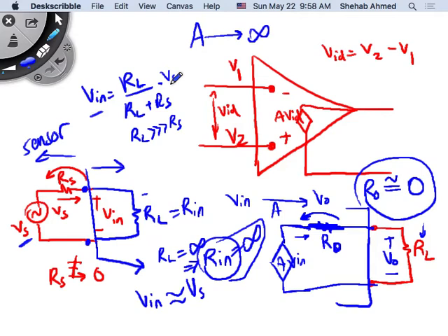So then the equivalent circuit becomes like this. We have an equivalent circuit for the input that looks like this, and an equivalent circuit for the op-amp output that looks like this. This is very similar to the voltage amplifier equivalent circuit that we introduced in chapter 1. And this is the workhorse of the op-amp's equivalent circuit. We will utilize this equivalent circuit, which is basically an input impedance and an output dependent source with a resistance in series, to model the op-amp. This is the only one we will use for the op-amp, actually. And what else?